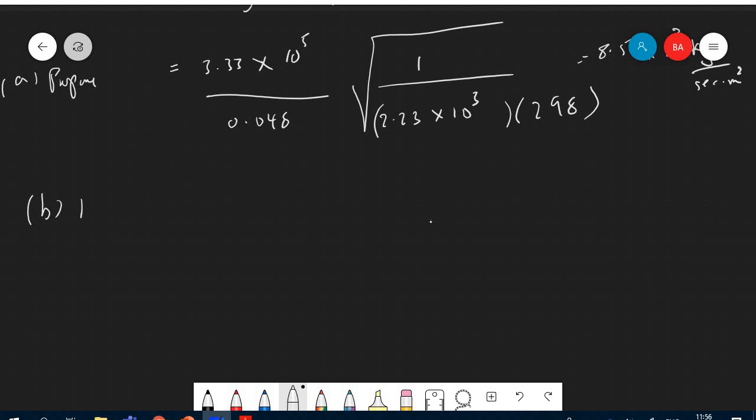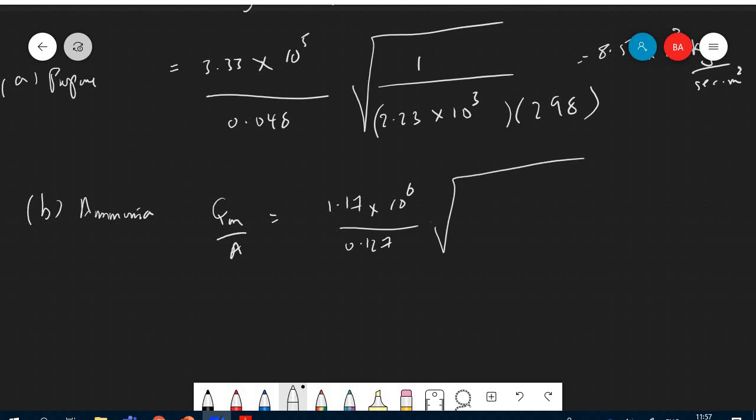I don't want to say it's just a straightforward kind of calculation. From this flux, of course, you can get a lot of information. If you know the area, you can know how much Qm is. If you know the area of that hole and you know Qm, and you know the ventilation rate, you can compare the concentration in ppm with the threshold limit value. So there is a lot of information that you can gain out of here. This is just practice for what you need to do.